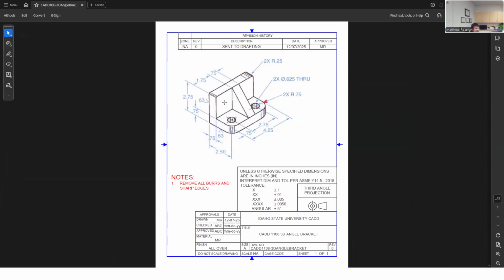Oh, and I also discussed that I'm going to view this as my front view, these surfaces here, looking straight at that gusset. This will be a gusset piece here. The back side of this view will become my right side view, and then I'll also have a top view of this one. I think that will be good for details. We'll have the longest width, a nice stable part profile, exposing some features. So that'll be a good front view choice.